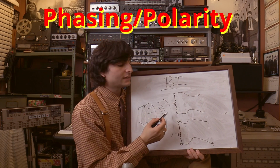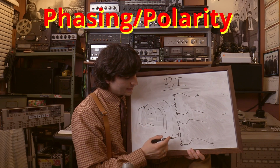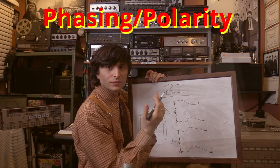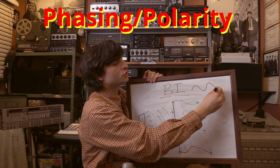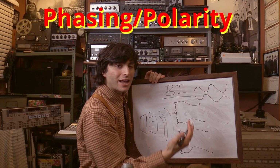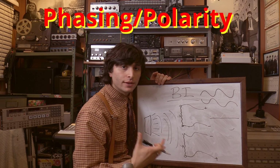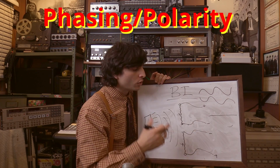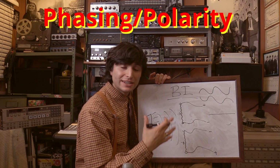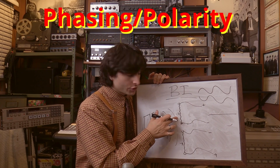You are going to be seeing a positive voltage from the first microphone while seeing a negative voltage from that second microphone. And when that happens, those two audio signals are going to cancel out completely, and you're going to result in no signal at all. Now, obviously, this is an extreme example, but this polarity issue can manifest itself in different ways in the studio if you're not thinking about the polarity of your ribbon microphone.